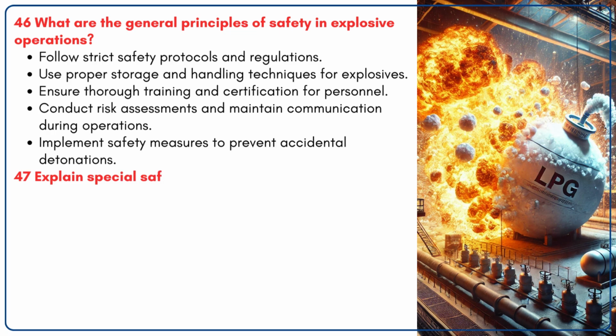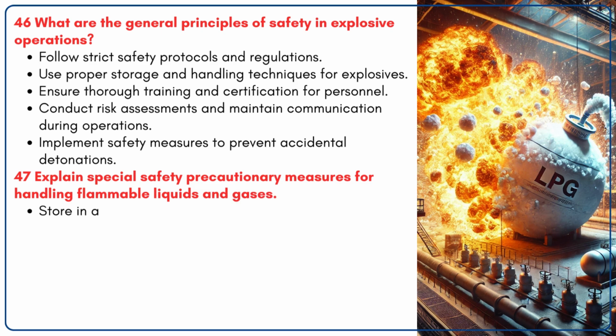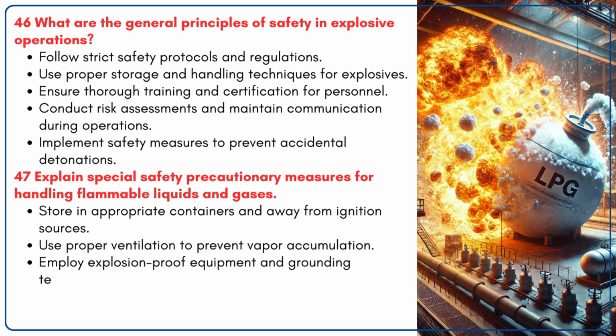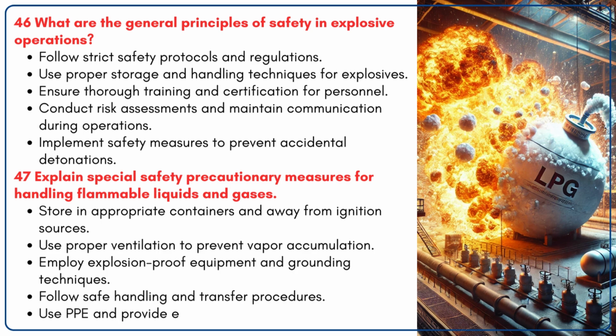47. Explain special safety precautionary measures for handling flammable liquids and gases. Store in appropriate containers and away from ignition sources. Use proper ventilation to prevent vapor accumulation. Employ explosion-proof equipment and grounding techniques. Follow safe handling and transfer procedures. Use PPE and provide emergency response training.